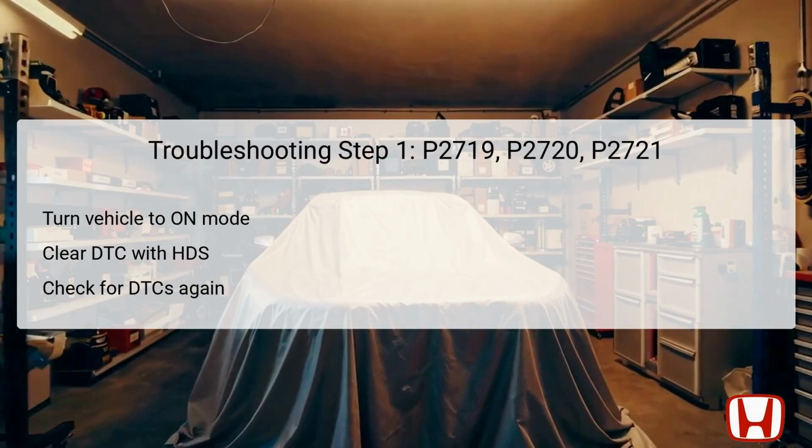The first step in troubleshooting these DTCs involves verifying the problem and ensuring that the appropriate diagnostic tools are used. Start by turning the vehicle to the on mode. This action powers up the vehicle's electronic systems without starting the engine, which is crucial for conducting diagnostics. Utilize the Honda Diagnostic System, HDS, to clear the DTCs from the computer's memory. Clearing these codes helps refresh the system and allows for real-time monitoring without previous errors clouding diagnostics.